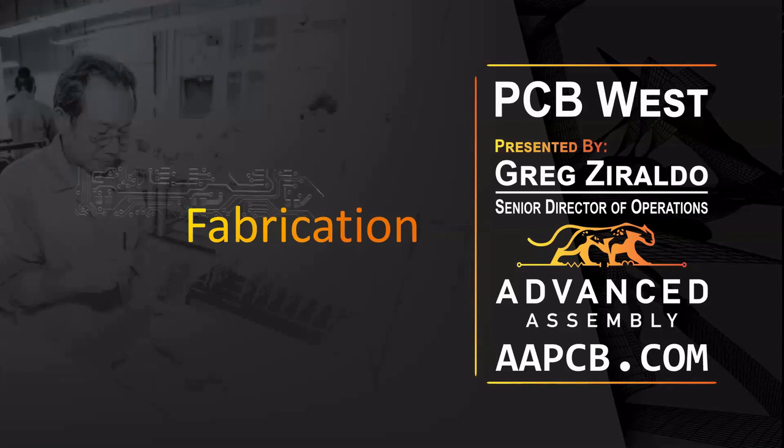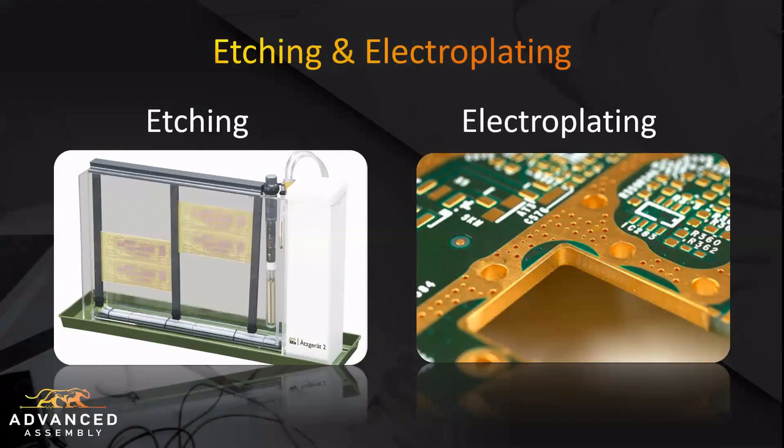So when we talk about fabrication, printed circuit boards are fabricated in dozens of steps. You can have basic circuit boards, 2-layer, 4-layer, that are built in 10 to 20 steps, and then you can have HDI and multi-lamination, microvia, copper fill that are 150 to 200 steps. The basic idea for internal layers is to remove copper in places that we don't want it, through etching. The outer layers of copper are built up through electroplating, and then they're etched after that. So etching is used on the internal and external layers of PCBs to remove copper.